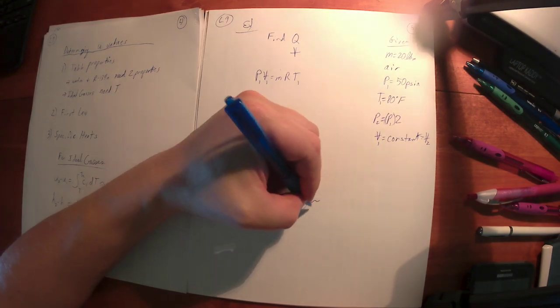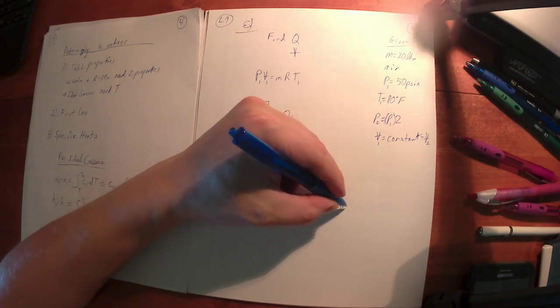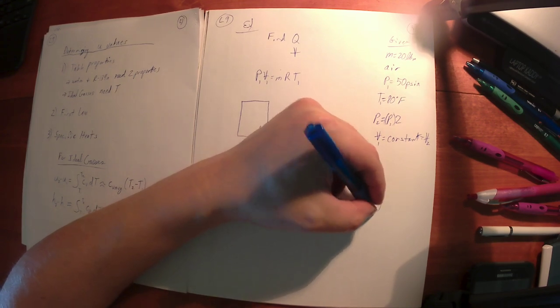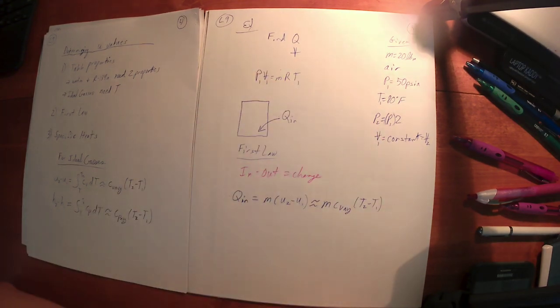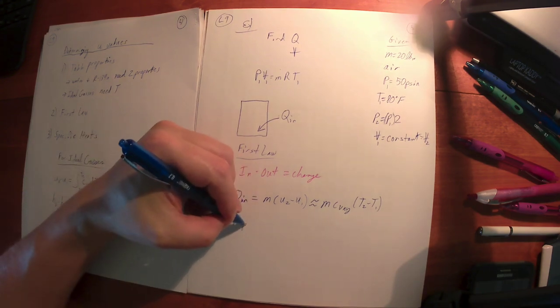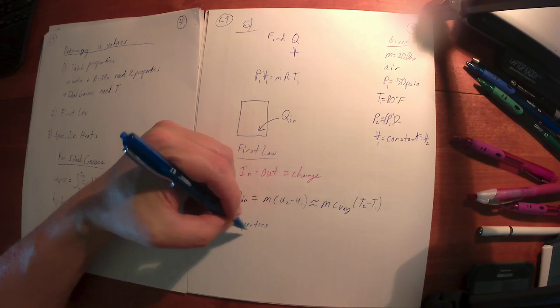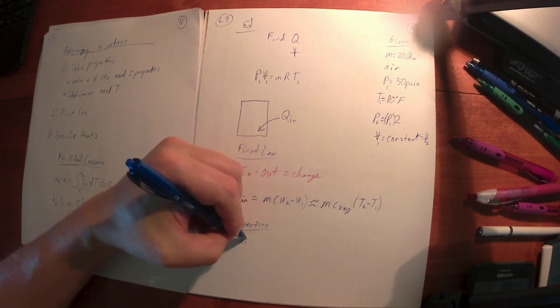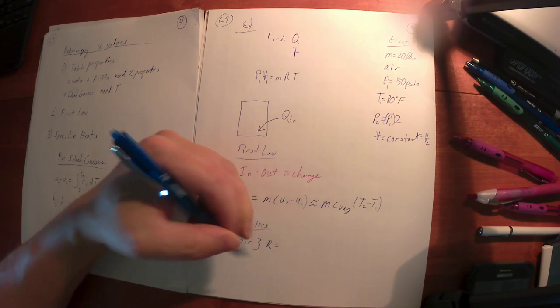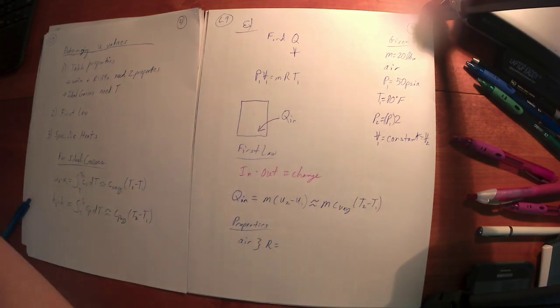So let's say that this is approximately M C sub V at the average temperature times T2 minus T1. C sub V gives us delta U. All right. So now I need a couple of properties. The fact that it's air is really all I need to go find the R value. So I need R value in English units. Let's see, which ones do I...